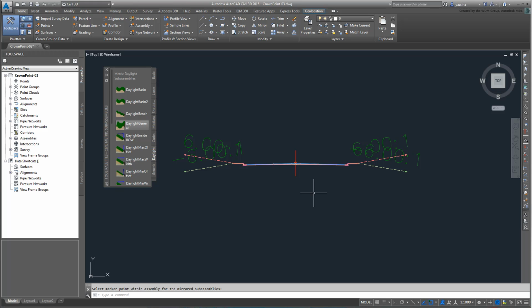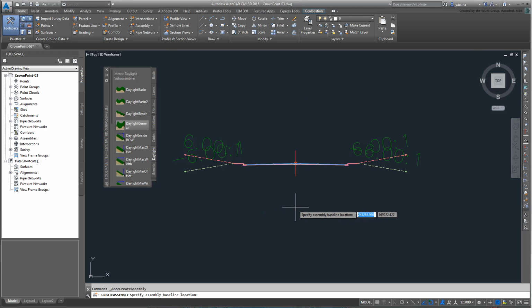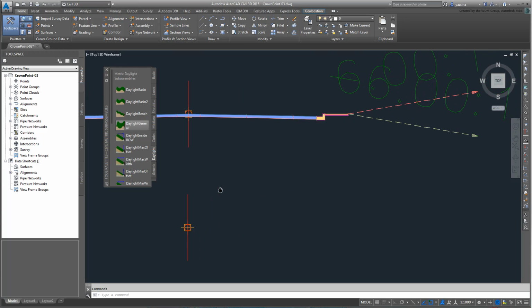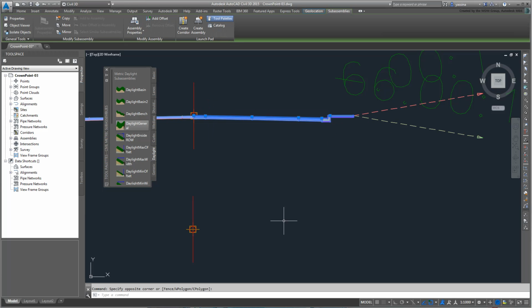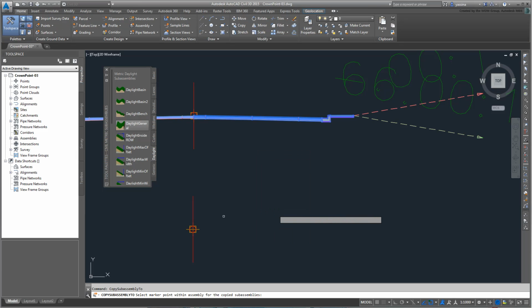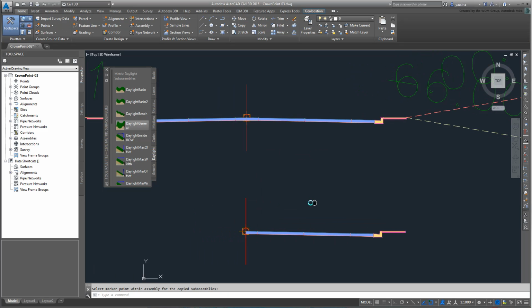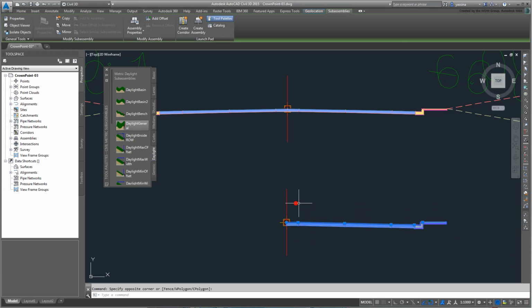First, start by creating a new assembly node as you did earlier. Name it Assembly Bridge Over Water. Place its node underneath the previous one. Now select all the components to the right of the first assembly except for the daylight part. Also make sure the original node is not part of the selection. Right-click and choose Copy To, and then click the new assembly node. You now have duplicates of the sub-assemblies you need. Select the duplicates and mirror them to the other side as you did before.